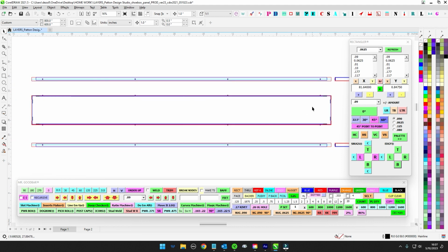So now we need to think of the backer, and how it's going to go on the wall. This is where knowing what hardware the install favors, and having installed a couple of times, is helpful. It's 100%: you've got to know what substrate this is being installed to. Is this going against a cinder block wall? Is it going against studs? Is it going onto another sign? If this is going onto the face of another sign, you're going to have a completely different type of layout than, let's say, a brick wall or something.